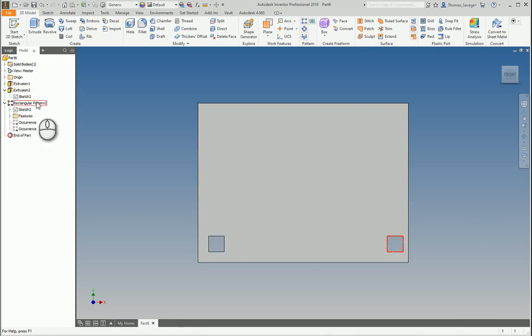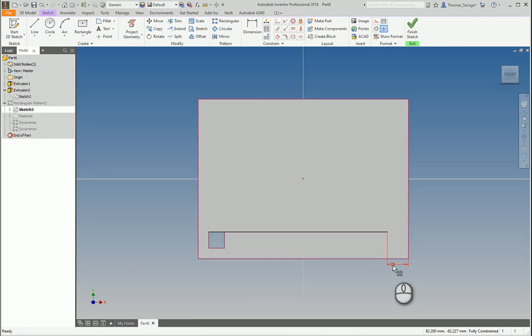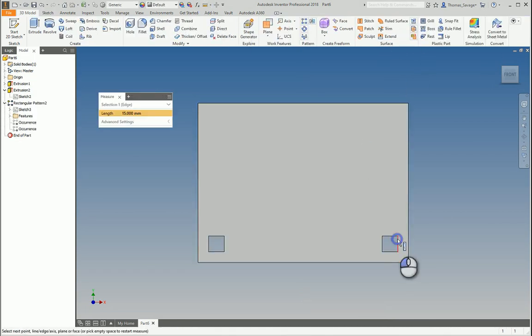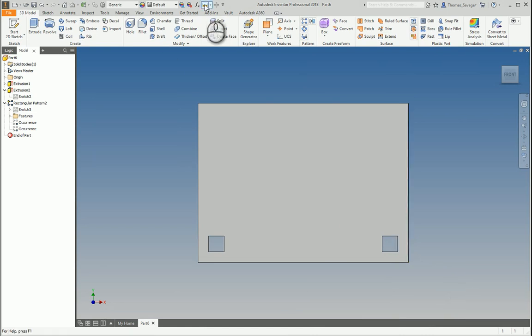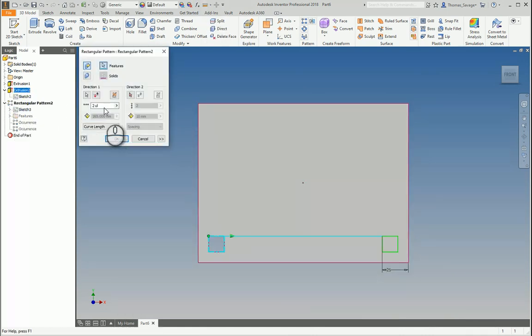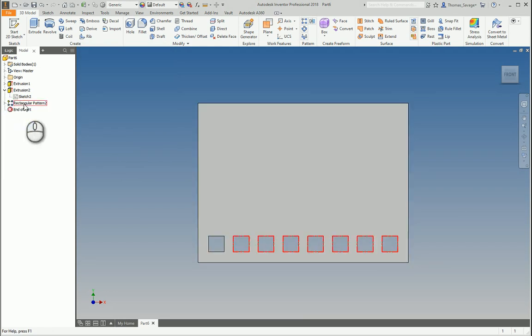And then under here will be our sketch that we just created. So we'll put that as 25. Right. See, now we have the same distance from there, which is 10, and there, which is 10. So now we can add in, if you see here, 165 mil. We can add in 5, and it will equally space 5. We could add 8. It will always equally space these occurrences.